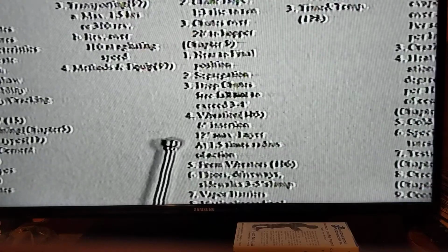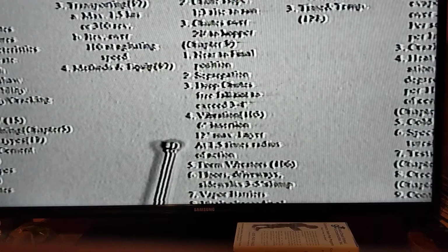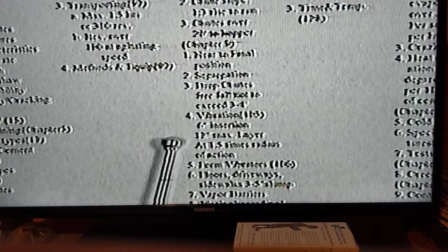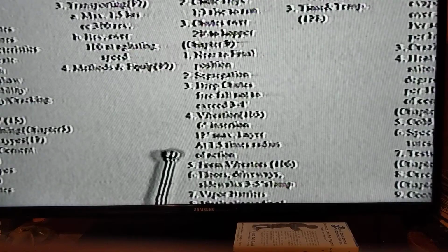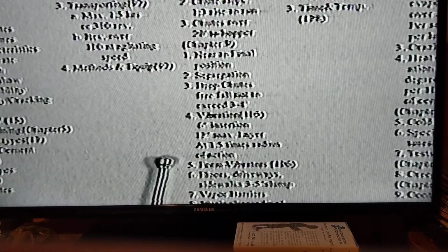And one way to create vibration is to use an insertion rod, which you would extend 6 inches into each layer with a 12-inch maximum layer. And you're going to want to move this very slowly, dropping it all the way to the bottom, at least 6 inches into the next lowest layer, pulling it back up very slowly, and then going no further as you move it along than 1.5 times the radius of action of this vibrator. In addition to this, there are form vibrators. For example, that column I spoke of a